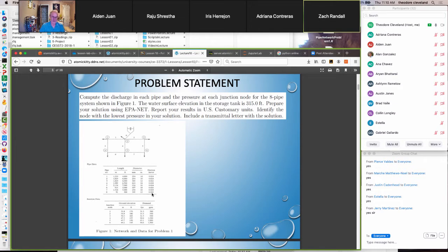So EPANET uses a type of Swamee-Jain equation approximation, and at certain input values that are typically encountered, parts of that equation go horizontal, so there's no change in friction factor with change in other features. So getting exact matches is essentially impossible. We should be able to match at least within order of magnitude and possibly within 20 or 30% of these published ones in this example.